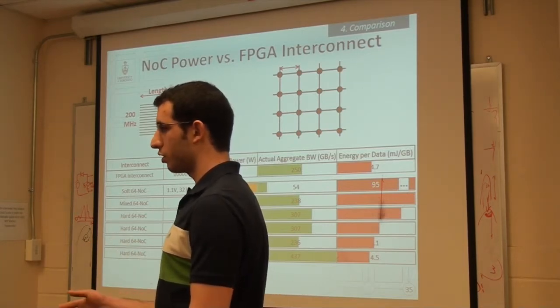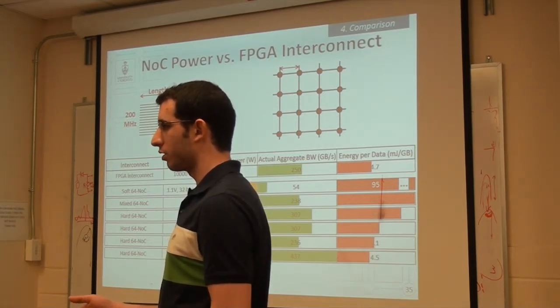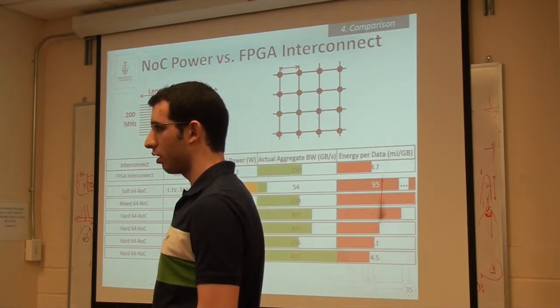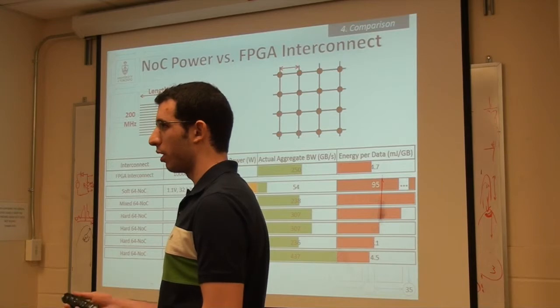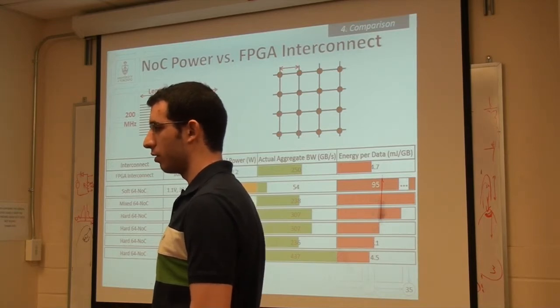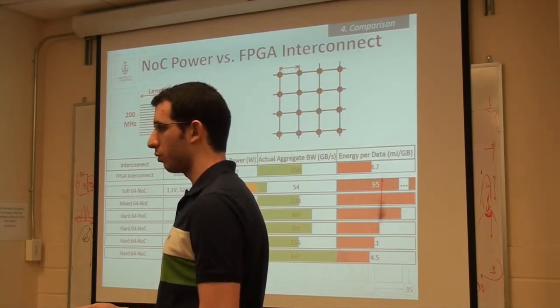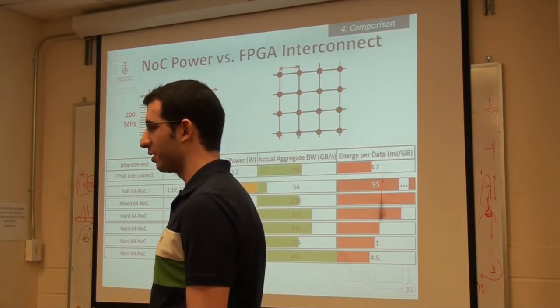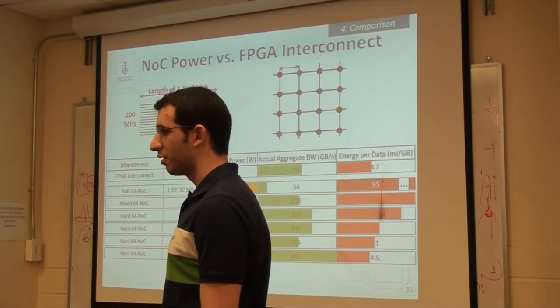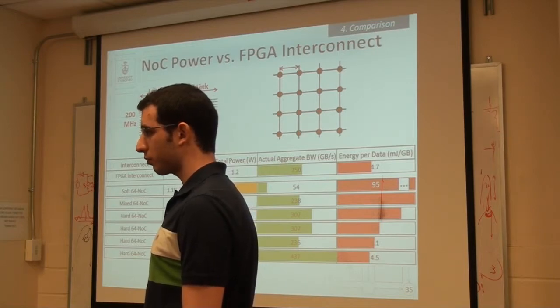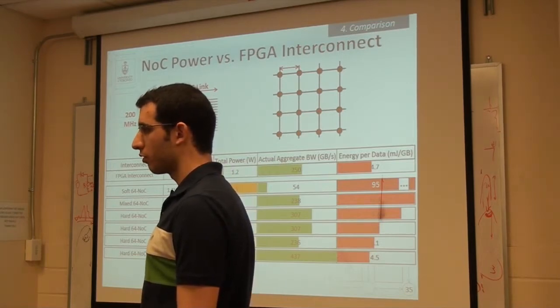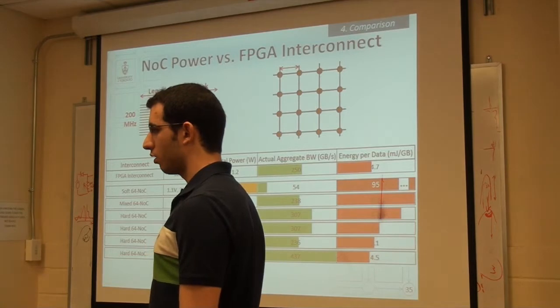If you have a very large system with a lot of things and not really any traffic priority, then yes, there will be some extra latency due to congestion, and you cannot predict that except through simulation, also an upper bound or a lower bound on this latency. But yes, that's what latency-insensitive design entails. Right? And for your particular configuration that you've simulated and tested, what is the absolute latency through one of your routers? Through one router, do you know, uncongested?